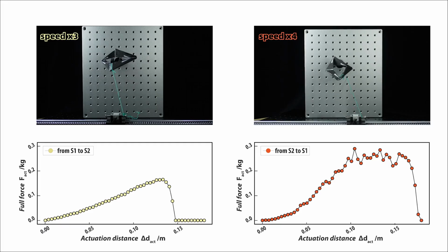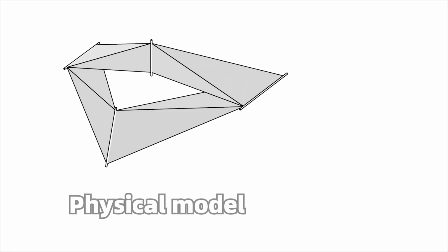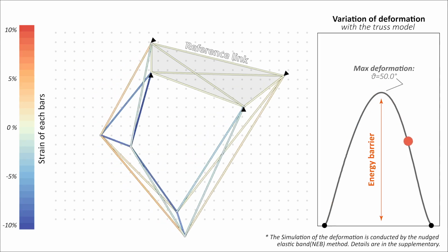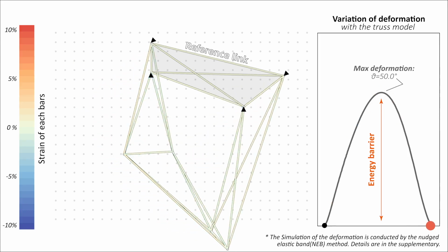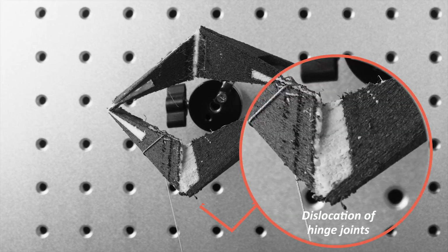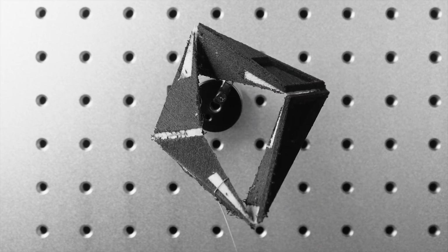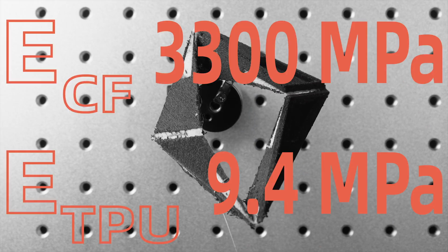The pull force along the reconfiguration indicates the resistance of the structural deformation when switching from stable states. If assuming all parts of the linkage are deformable, the reconfiguring simulation with a truss model gives an evaluation of the strain explicitly. But physically, the elastic deformation of joints contributes to the most part of the energy barrier because of the wide difference in Young's modulus between the two materials.